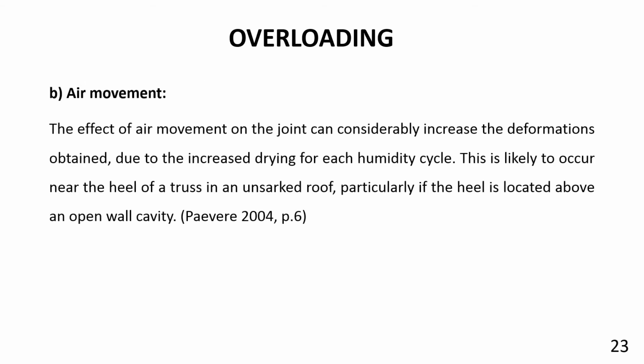Air movement. The effect of air movement on the joint can considerably increase the deformations obtained due to the increased drawing for each humidity cycle. This is likely to occur near the heel of a truss in an unsarked roof, particularly if the heel is located above an open wall cavity.